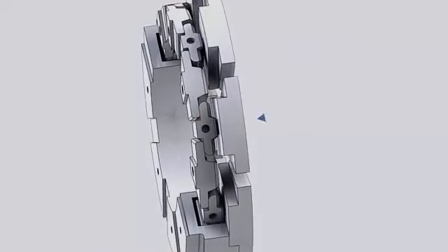The load transmitted by the thrust runner to a single pad causes the pad to press on the upper leveling plate right behind it. Each of the upper leveling plates in turn is supported by one edge of two lower leveling plates. The other edges of the lower leveling plates take part in supporting the adjacent upper leveling plate on either sides. As a result of this arrangement, any excess of thrust load on a single pad is immediately shared through the leveling plates, so that all bearing pads will automatically receive equal loading.